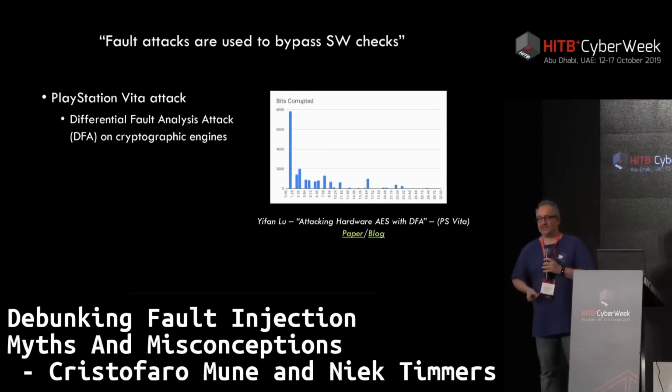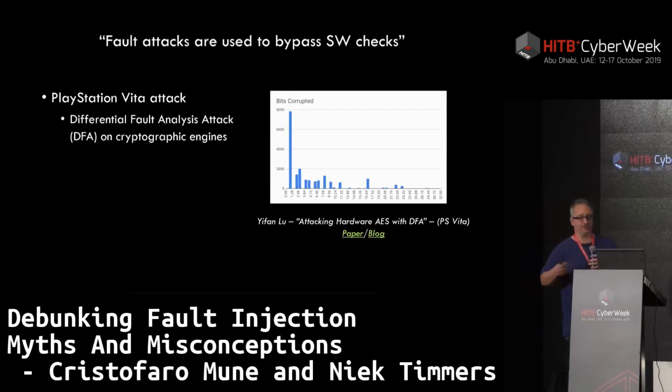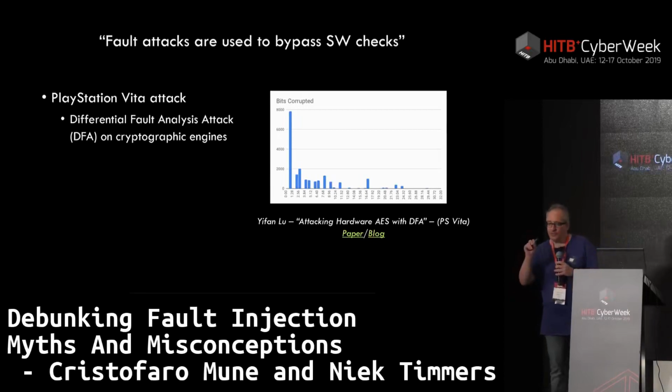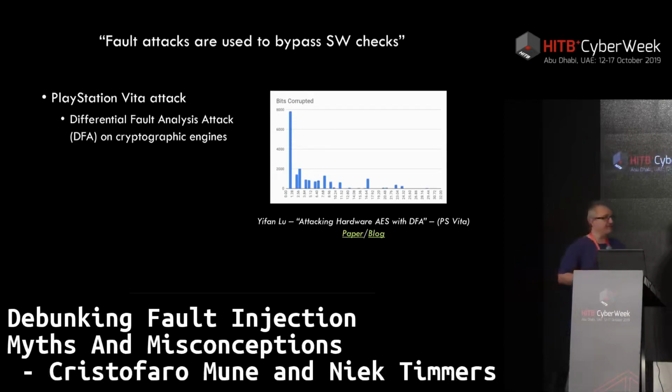So there are a number of attacks which are called differential fault attacks, which rely on the fact that when you inject a glitch in a crypto calculation performed on the hardware engine, chances are that it will give you a faulty output, a wrong one. And there are techniques elaborated and investigated by academia that if you collect enough of these faulty outputs and the glitch happens at the right point in time, you can reconstruct the public key. You might think of this as a pretty mythological attack.